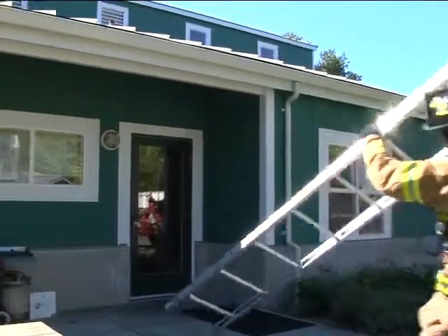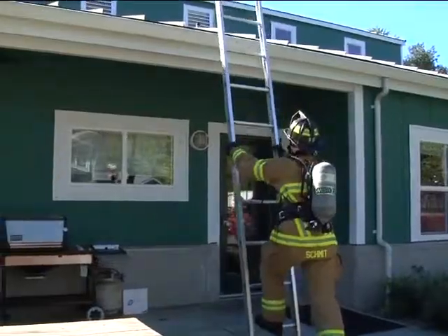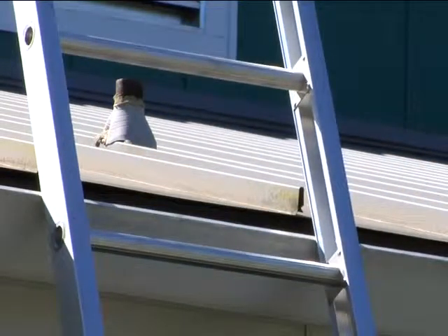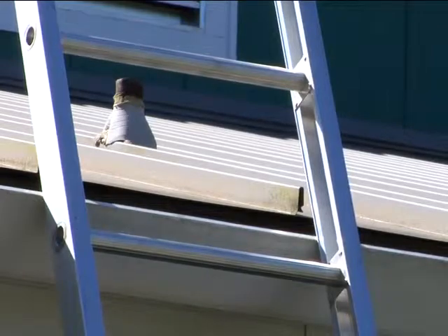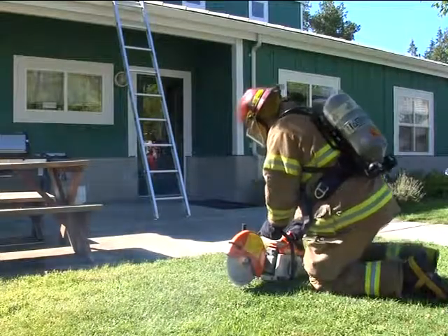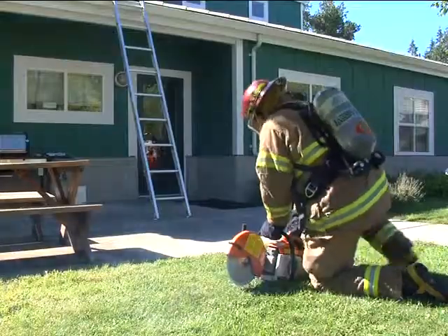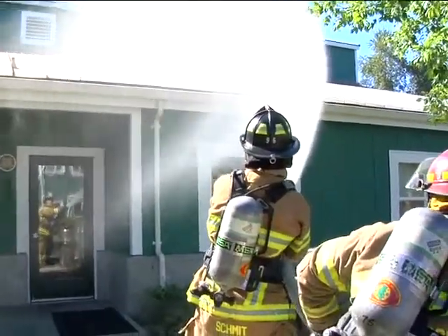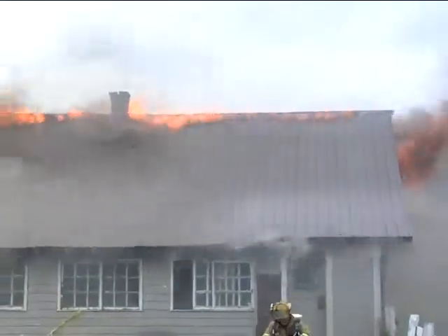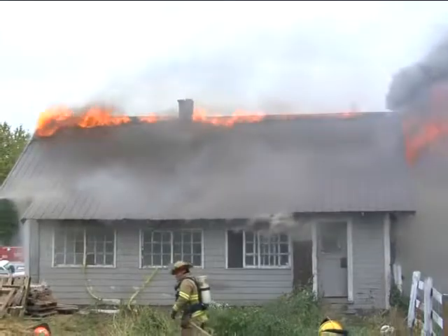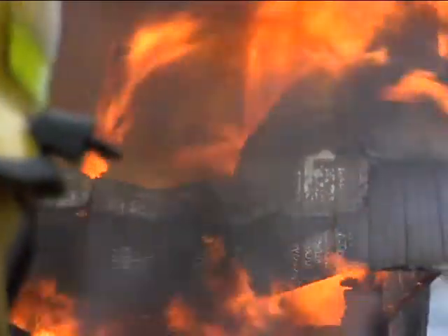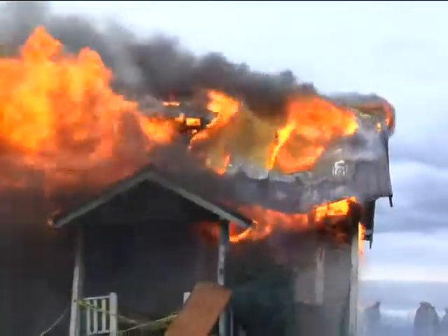Metal roofs and metal roof decking are a special challenge in vertical ventilation. They are slippery and conduct heat more quickly than other materials. Special blades for cutting metal must be used. Firefighters may use hose streams to cool the roof down. Be aware that a heated metal roof may melt roof decking materials, causing dangerous flammable vapors to be released and fire to spread rapidly under the roof. Because metal roofs are supported by lightweight trusses, they may fail quickly with limited fire exposure.